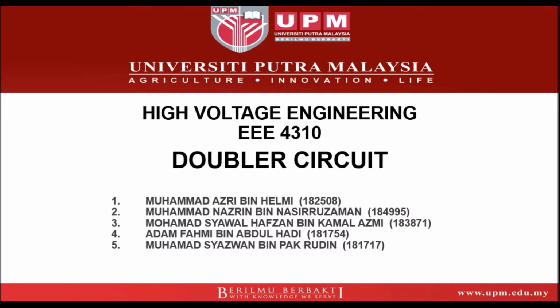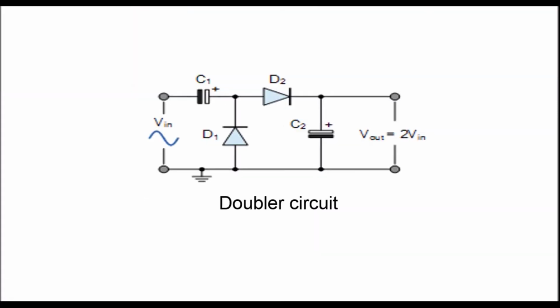Okay, a voltage doubler is a voltage multiplier circuit which has a voltage multiplication factor of 2. The circuit basically consists of only 2 diodes, 2 capacitors and an AC input voltage. This simple diode-capacitor pump circuit gives a DC output voltage equal to the peak-to-peak value of the sinusoidal input. Voltage multipliers are similar in many ways to rectifiers in that they convert AC to DC voltage for use in many electrical and electronic circuit applications.